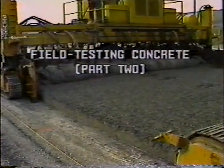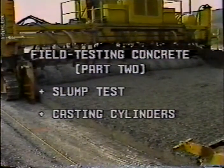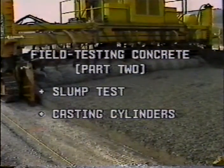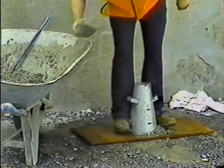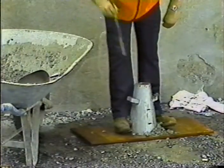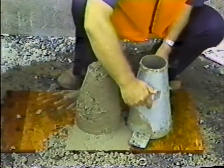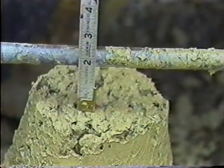Field Testing Concrete, Part 2. This program covers the slump test and casting cylinders for compression testing. We'll start with the slump test. Basically, the slump test consists of filling a standard slump cone with concrete, rodding it to consolidate the concrete, then lifting the cone off, and measuring how far the concrete slumps down when it's not supported by the cone.